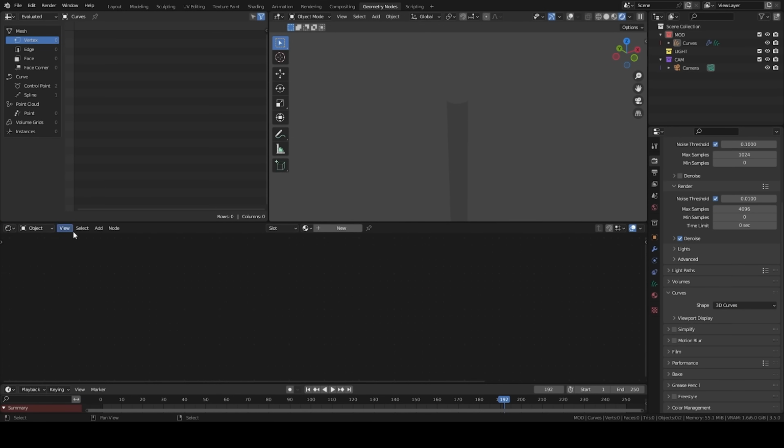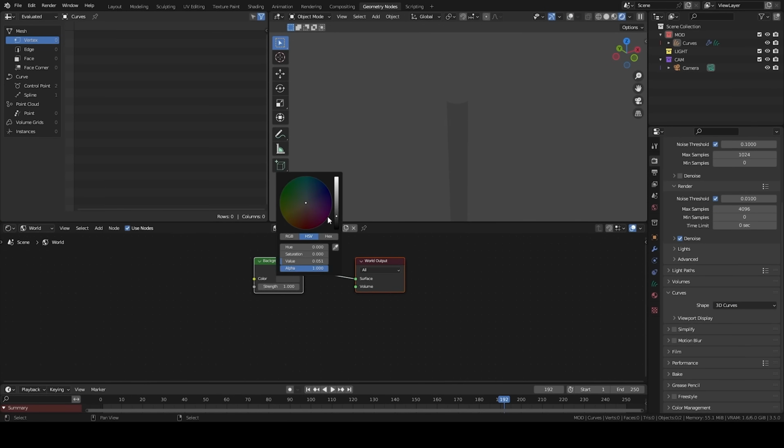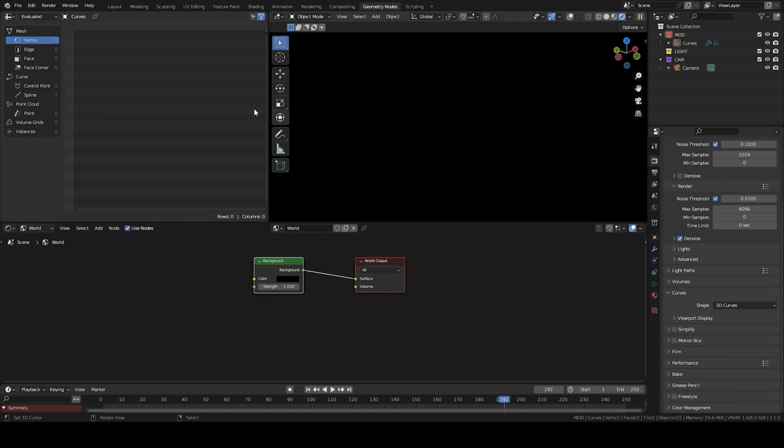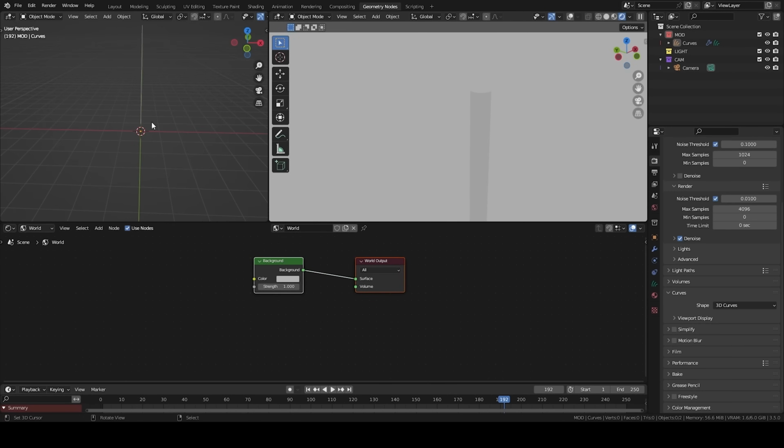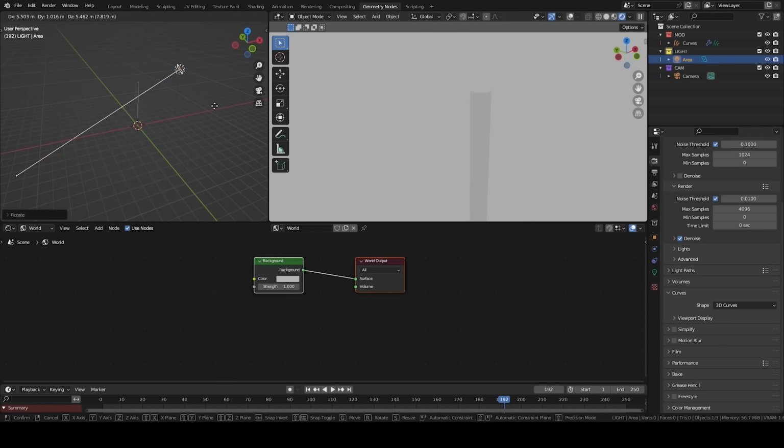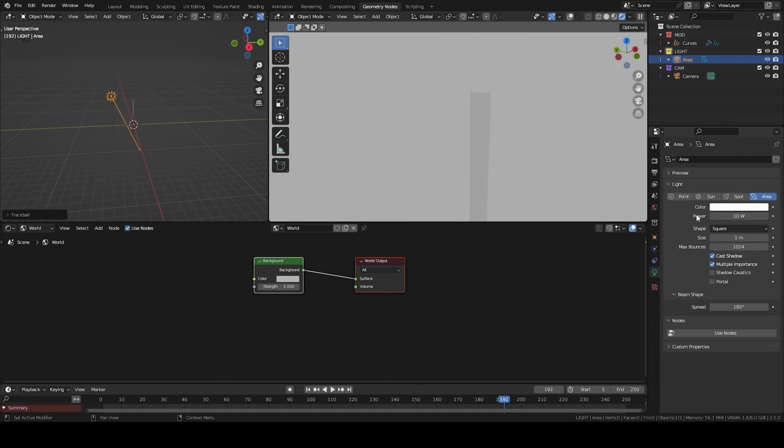I want to bring more light into the world by creating a brighter light. I'm going to 3D here. I'm doing Shift A by selecting the light collection, create light area, set a little bit aside over here, and we're going to give it a little bit of power. That's it. And this curve now, it's rendered as a primitive with an infinite level of detail.